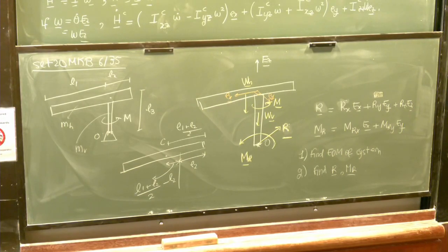Essentially, you said earlier the products of inertia are not going to be zero. At least one of them is not going to be zero. That's right, you tell me which one. The thickness is just zero, and they're all in the z there. So the moments of inertia and products of inertia about the center of mass are going to be zero. I see xz, I see yz. These two terms are zero. But they're not areas, they're distances.